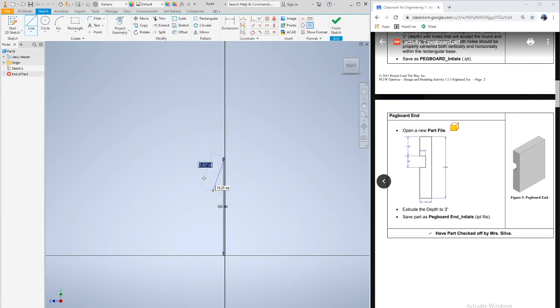And then we're gonna go to the left, sorry. To the left, we're gonna go 0.75, and again, make sure it's a perpendicular angle, so either 90 degrees or 0 degrees, depending what angle you're building at. I'm gonna go ahead and click, and then I'm gonna go down 1.25, I believe, and make sure that's a 90-degree angle again. There it is. I'm gonna go inside 0.375, and again make sure it says 90 degrees. And I'm gonna go down